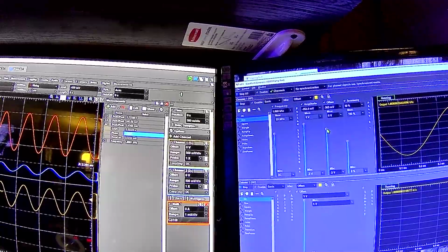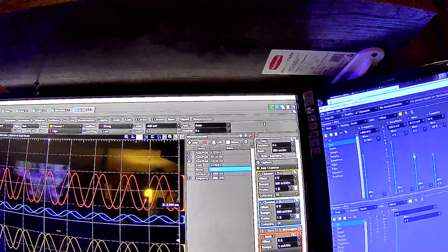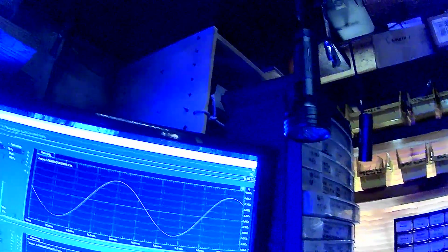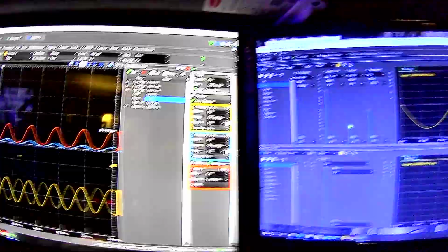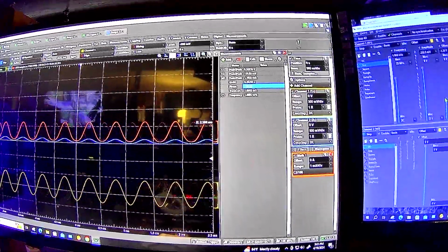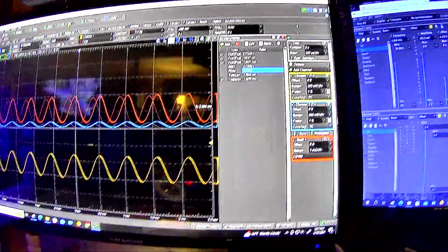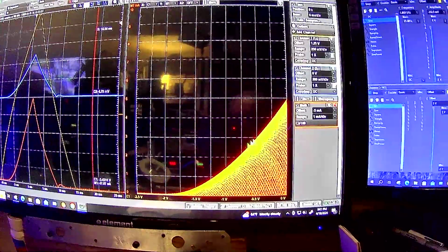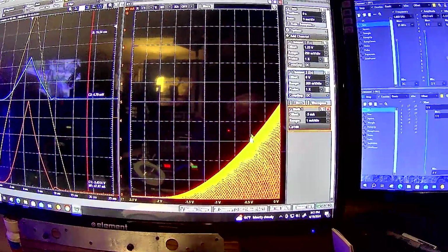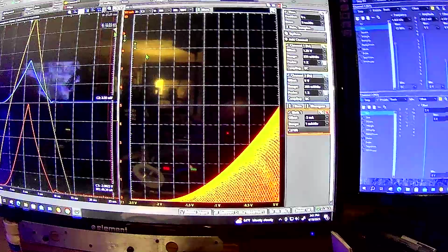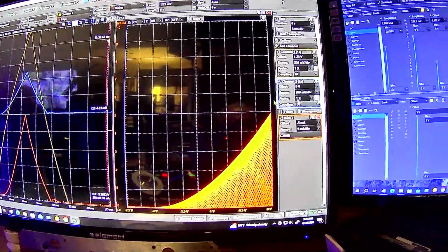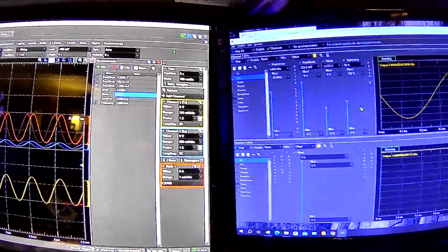Okay, but let me try to see if I can 565, and let's see. Oh, good, look what's happening. Our transconductance is changing now. So down to 2, down to 1, as I vary this, and we're still definitely in the negative voltage territory, so those are still appropriate signals. So yeah, that's what I expect. The transconductance should change based on where you're at on this curve, where your Q point is and amplitude and everything like that. Your transconductance is going to be different here than it is here, and even slightly different there. Transconductance supposedly gets lower here. It's a lower slope, a smaller change of current with respect to voltage. So you expect the transconductance to change as you move closer to a negative operating point.